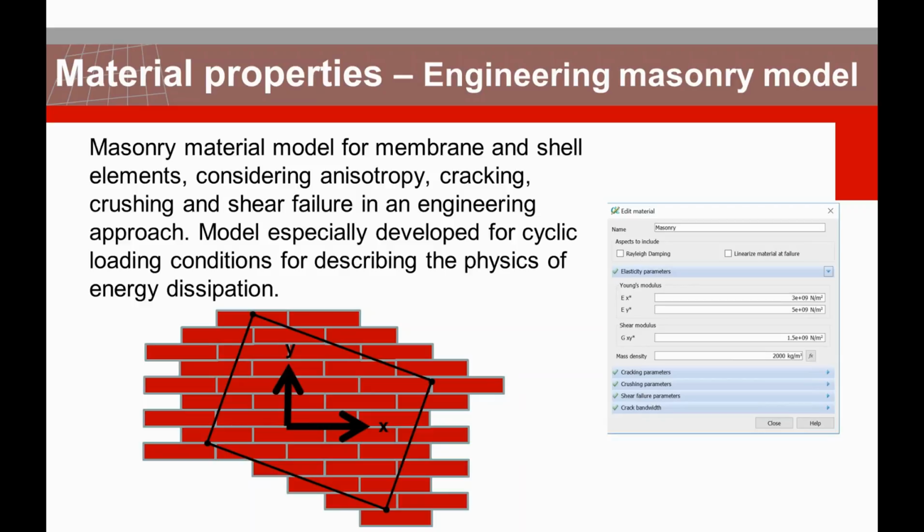This model is based on the anisotropic behavior of your masonry, and it is able to capture compression, shear, and crushing behavior. And in case of shell elements, you can capture in-plane and out-of-plane shear failure of your masonry models. What is important here is the position or alignment of the bricks.